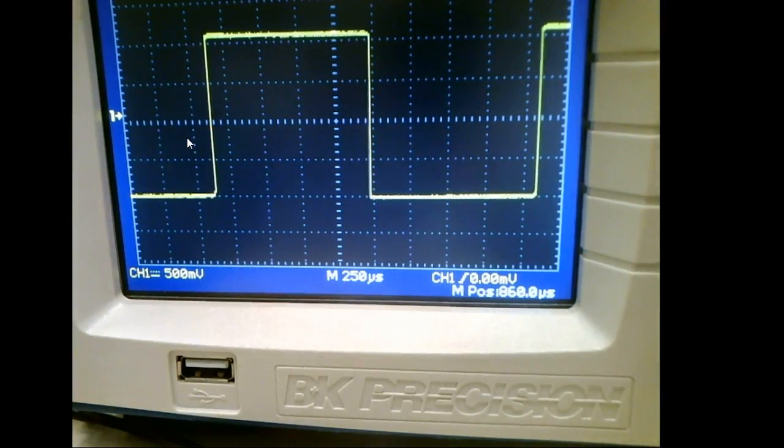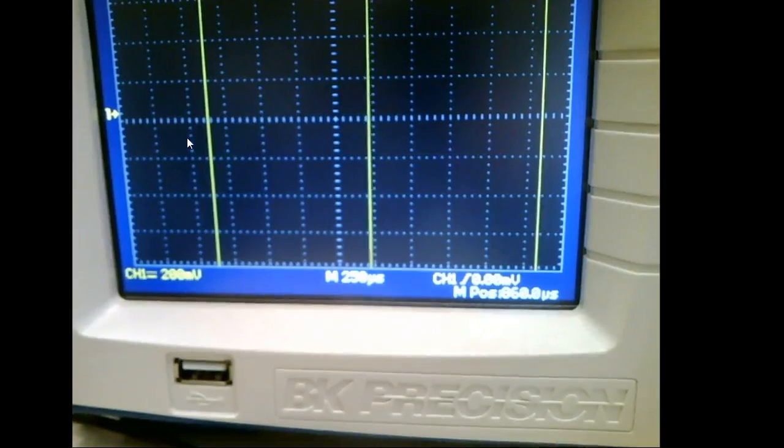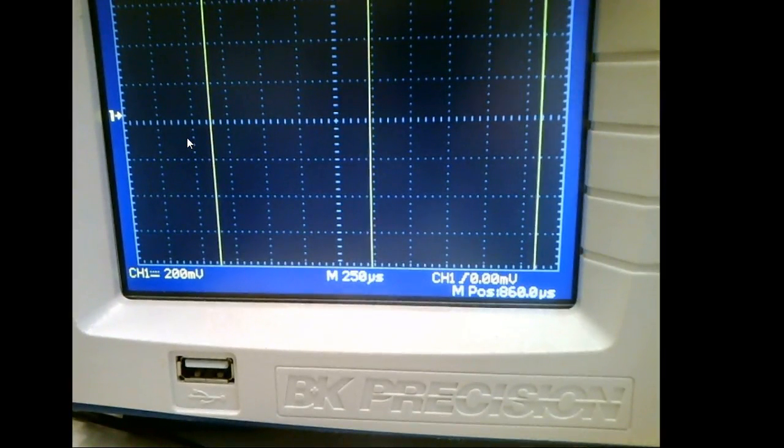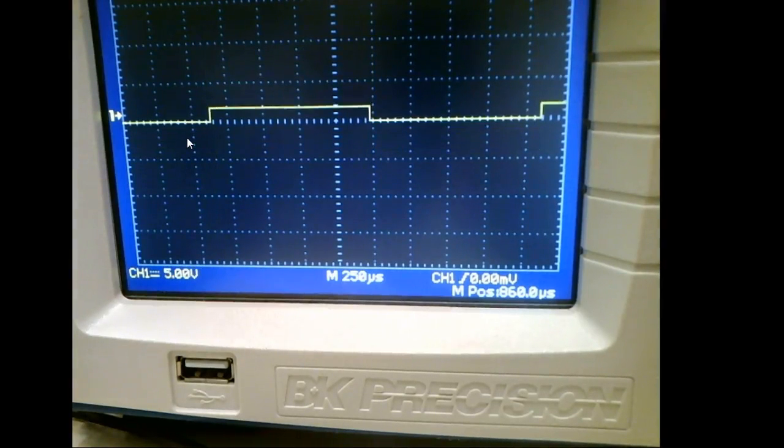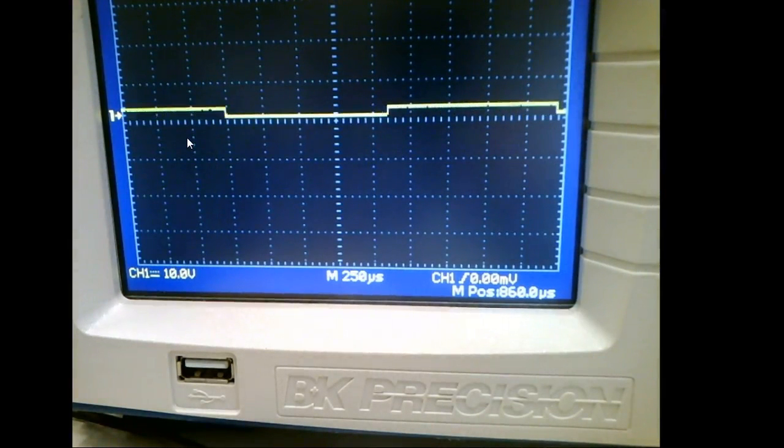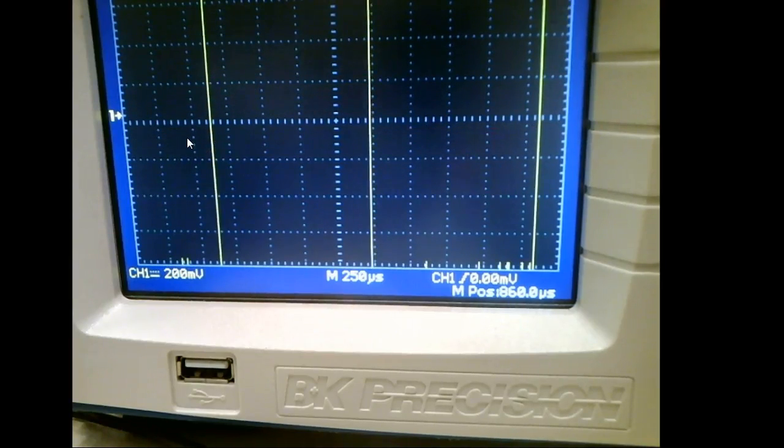Now the next thing I'm going to do is, I can't measure the voltage. Why? Because it's going off the top and the bottom of my screen. I can't measure the voltage now because I'm trying to put too much information inside a single scale, right? So what do I do on my voltage? Well, I turn it up as high as I possibly can and still keep it on the screen.